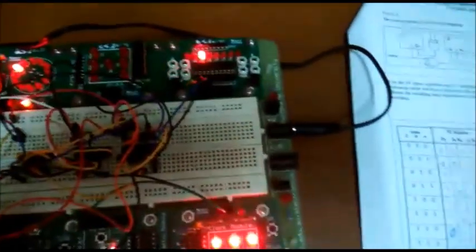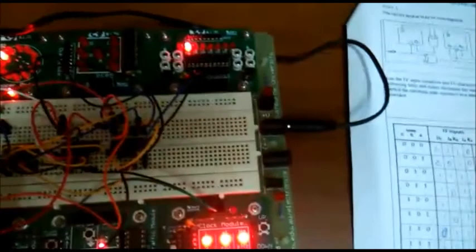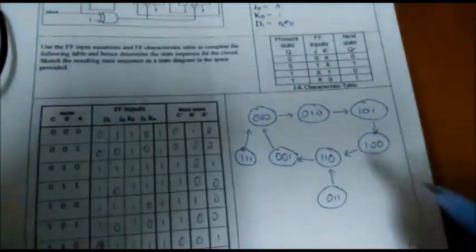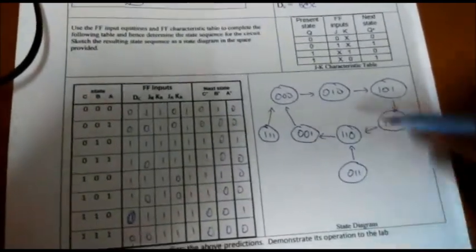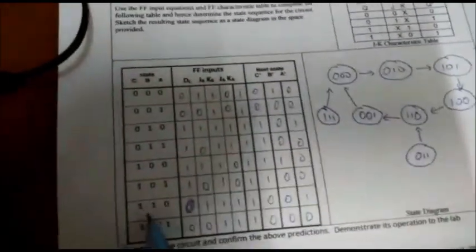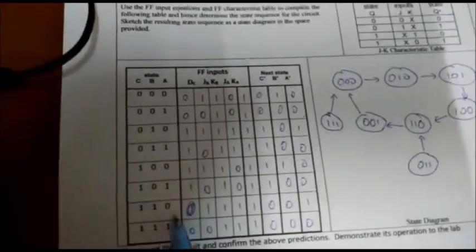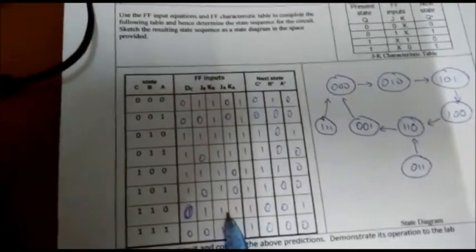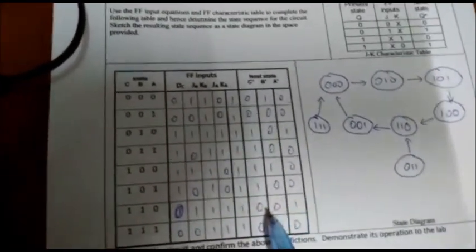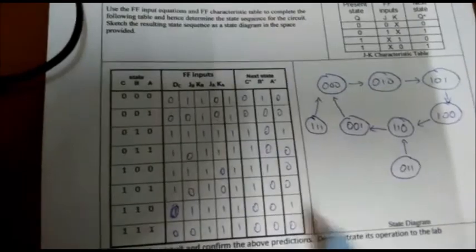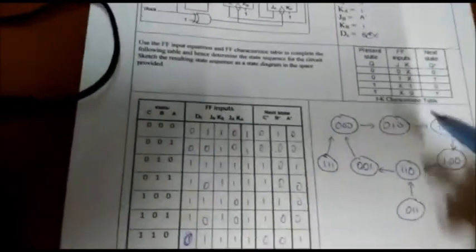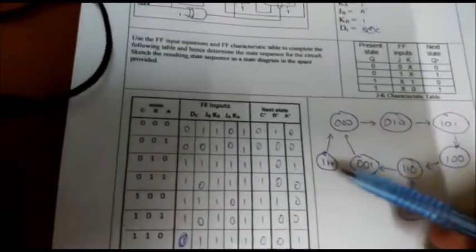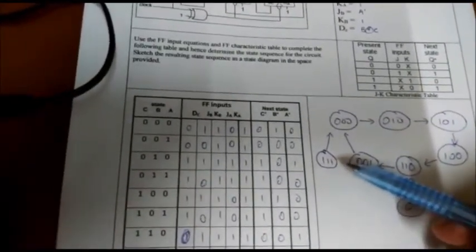And this will keep on looping unless we force a certain value to allow the transient state to be checked. So if we want to check 0, 1, 1, we need to look for the 1, 1, 0. So from this 1, 1, 0, if we change the KB to 0, the next state will change accordingly to 0, 1, 1. Hence, check. So likewise, we can do the same thing to 1, 1, 1 if we want to check 1, 1, 1.